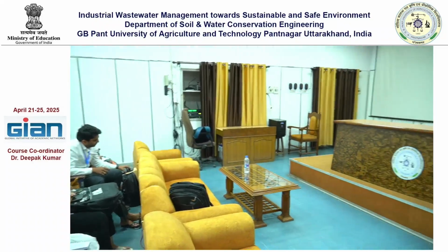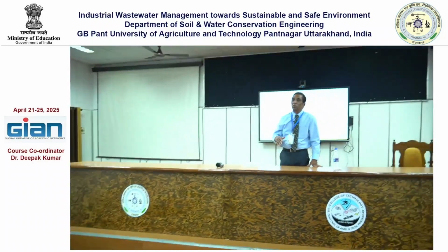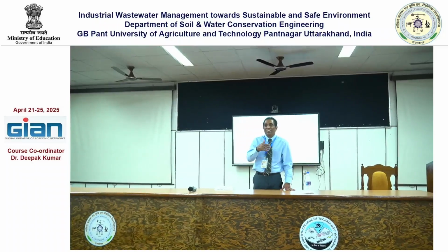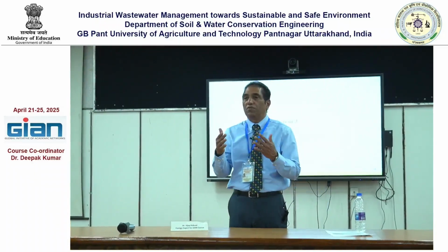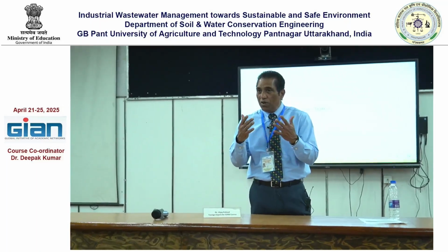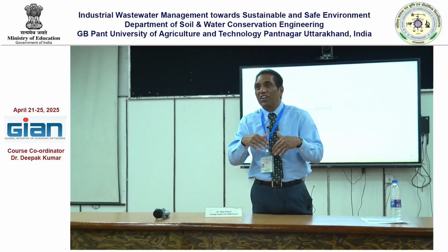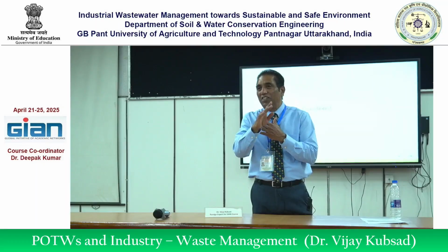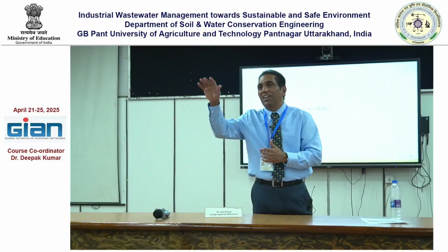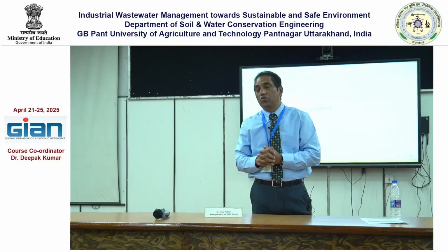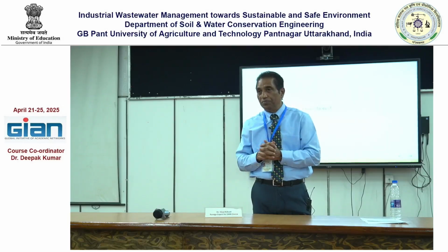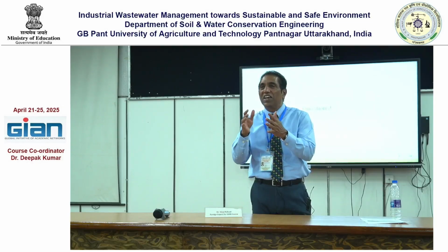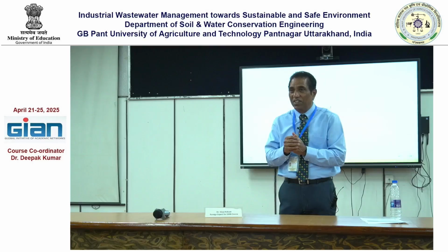Even if the quantity is humongous, that is why we try to remove as much of the water content as possible. The very purpose of the thickener I mentioned is to remove water from the solid. We want to remove water from the solid, then the water is recycled to the treatment plant, and the solid is taken off. Even if we are using it as manure, we remove water content in that. We want to make it as dry as possible. You cannot make it 100%.